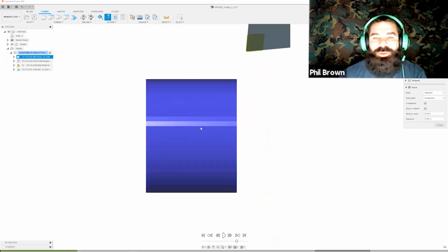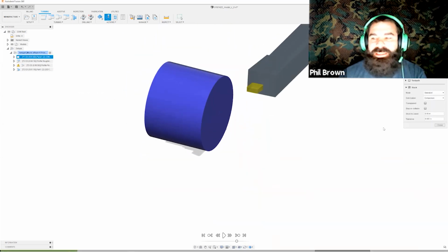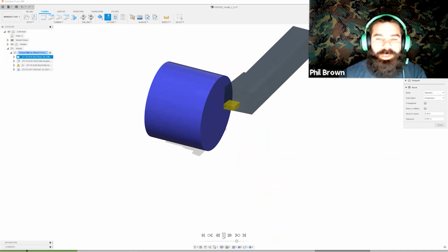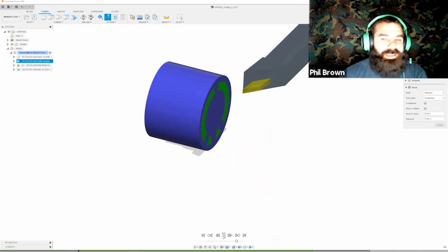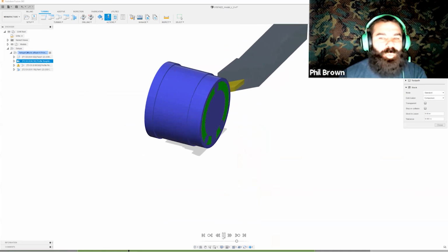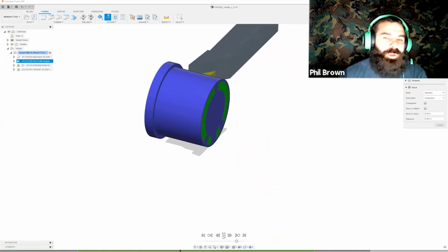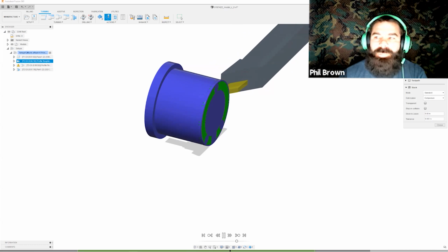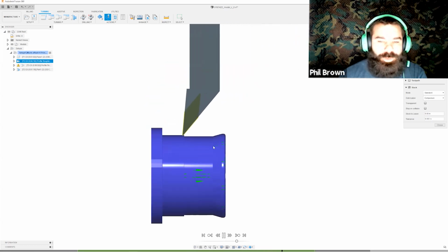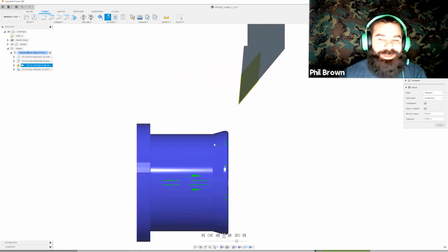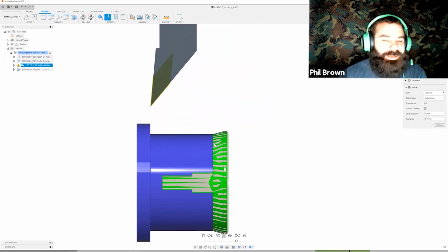So let's go ahead and simulate this tool now, and let's see what we get for a part. I'm going to hit play, and you're going to watch this as it does its facing cycle. It swapped out tools. It went to my nice cleanup tool, and now it's doing that outside roughing. We're going in from that weird angle, and we're doing that undercutting. Lastly, we're going to come back around and do one clean swipe all the way around.